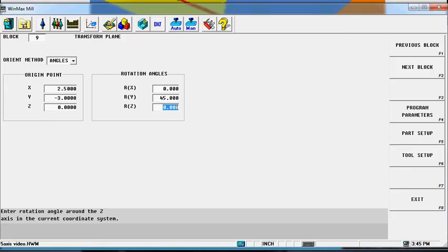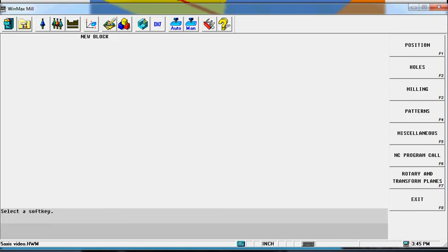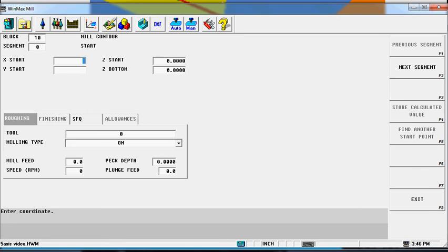Now once I'm there, I'm going to mill using lines and arcs. The very edge of that is my 0. So I'm going to leave my X at 0. I'm going to use the center of the tool and run the center of that tool down along what is now my new 0 point. So I'm going to leave X at 0, and I'm going to start at the end closest to me. So my Y is going to be minus, let's do 1.5 inches just to make sure that tool is starting off the part. Maybe I'll start at 0.1, but I'm going to end at 0.